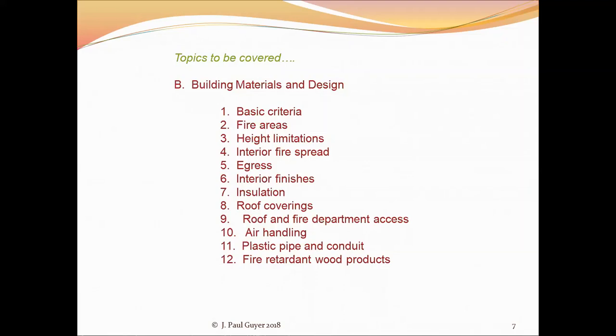And this stairwell serves not only for providing fire department access to where the fire is and to the roof, but it also is an egress route for the people in the building to get out of the building. Fundamentally, the egress routes are stairwells and corridors. And it's important that they maintain their structural integrity long enough to allow the people to get out of the building.